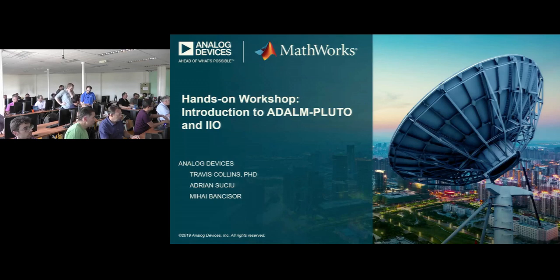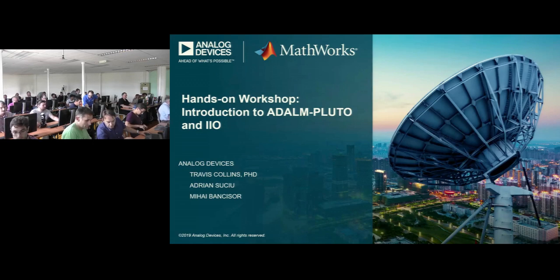I never tried this either. So if you try one of the older files, the mat files, they're loading. What language is your machine? Why are you asking? There was a bug in older versions of OSC where the data formats sometimes get corrupted for non-English versions of Ubuntu. It's Spanish. Yeah, that's probably why. I think German and Spanish were the ones that broke. Yeah, that's what I was thinking, that the locale is messed up.